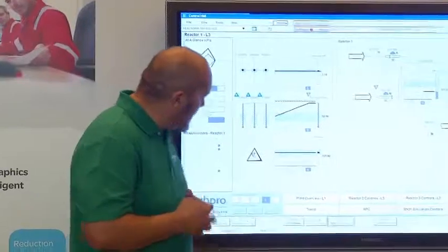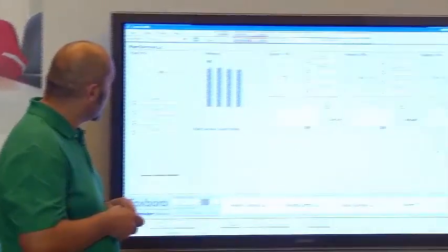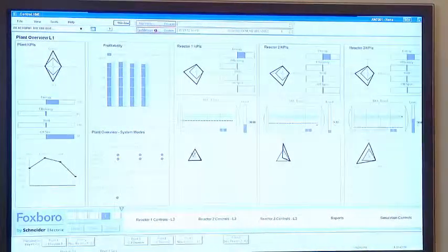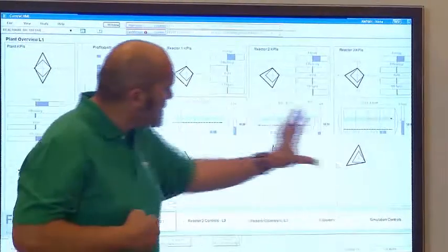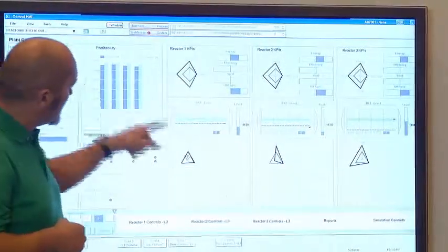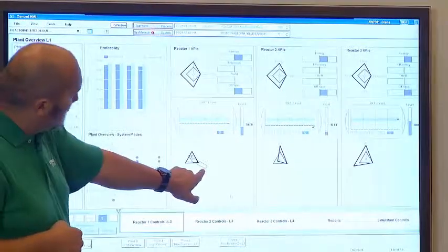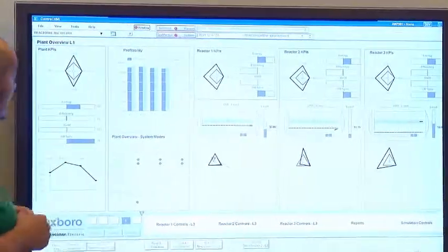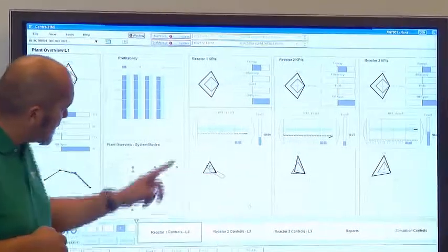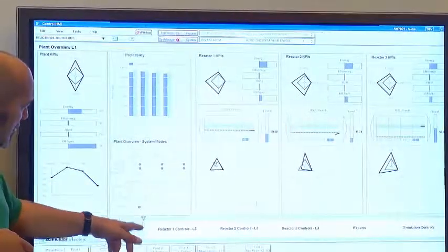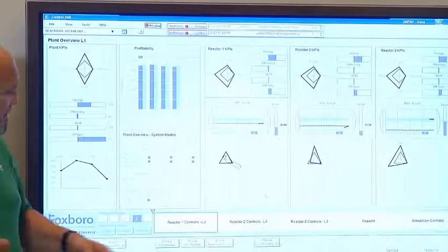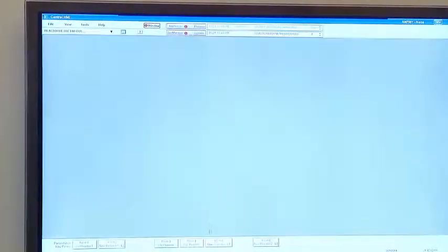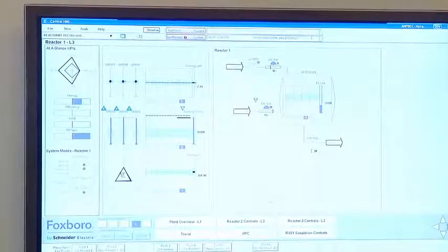Steve, if we could pop out to the overview display. When the operator looks at a more holistic view of his HMI, he can look at the entire plant overview and see that this alarm has occurred, pointing the way to the relevant process area. The alarm is also aggregated into his dashboard, so he can see the highest priority alarm being aggregated, allowing him to drill down, let's just click on that one, to really identify the root cause of why this is an issue.